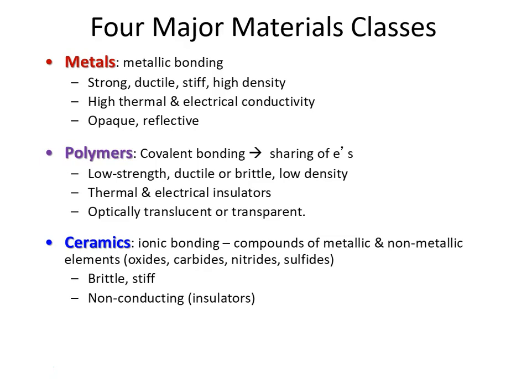The most important characteristic of ceramics in terms of design limitation is lack of fracture toughness, or they're very brittle. They can't absorb very much mechanical energy per unit volume of material. This is very limiting in how they can be deployed, since they don't resist propagation of a crack. So they can't resist high rate loading, thermal shock, etc., which tend to be quite prevalent in most engineering service environments. On the flip side, they are stiff and strong.